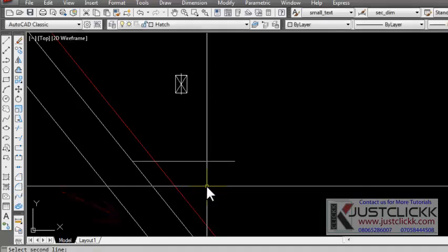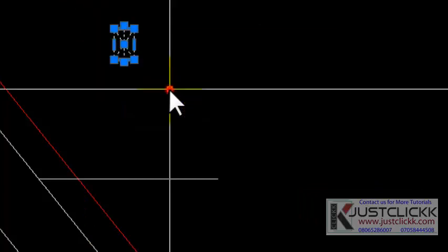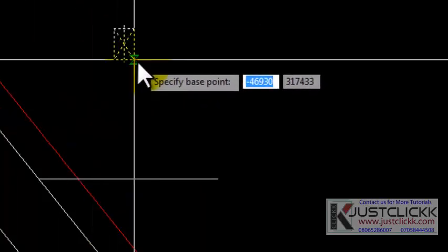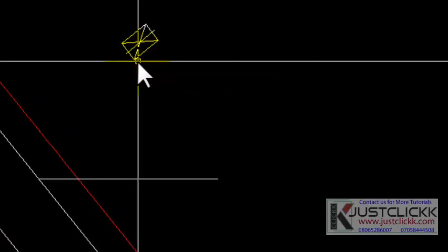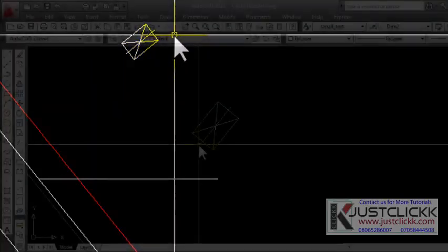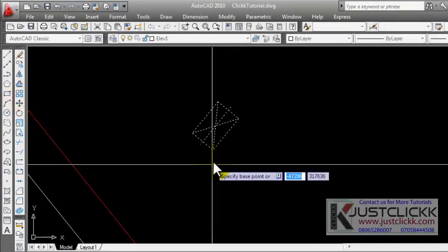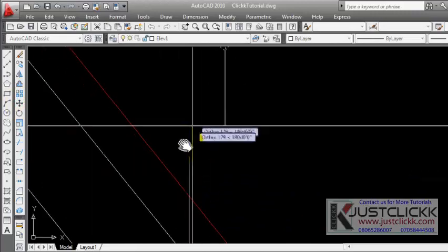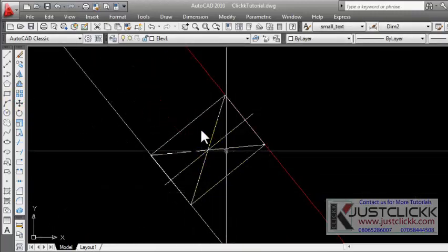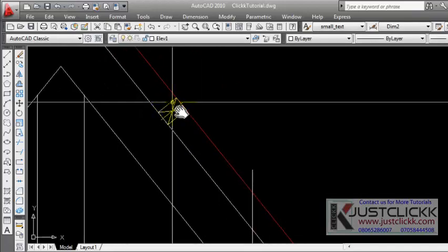So you press the escape key. That's just what you want to find. Then select this object and rotate it by picking the rotate tool, specifying a base point anywhere, and rotating by 51, and you will find the angle will be rotated in that direction. Alright, like so. And then move it down the edge, and that fits in perfectly. So that's how you can resolve such problems.